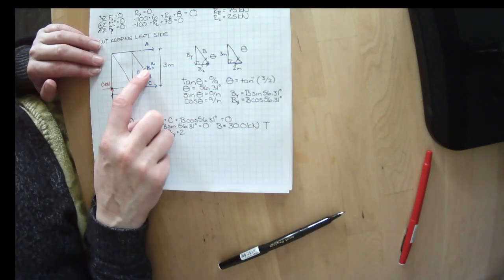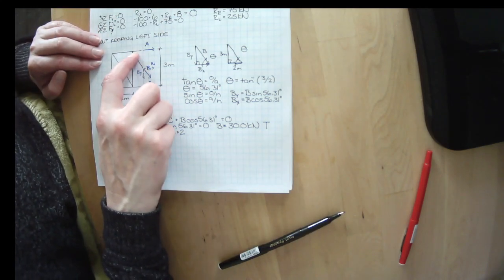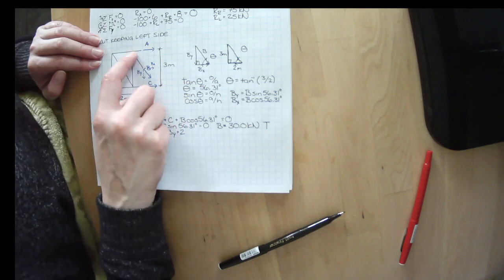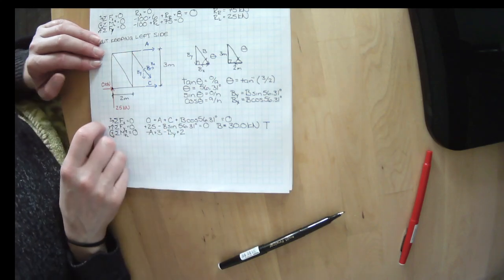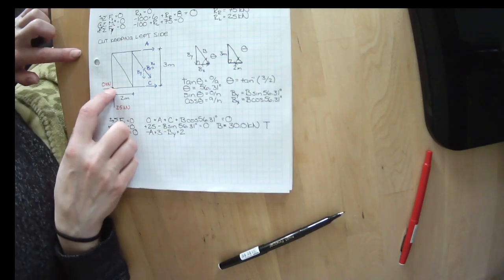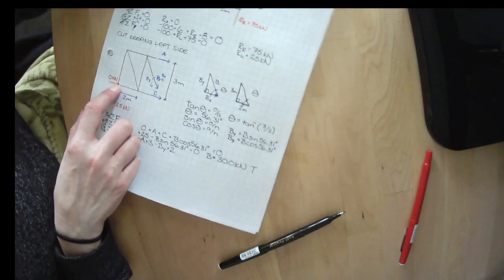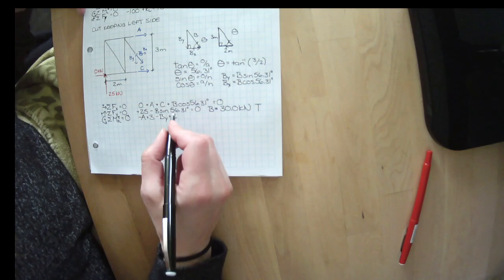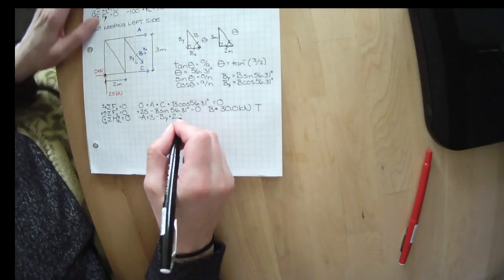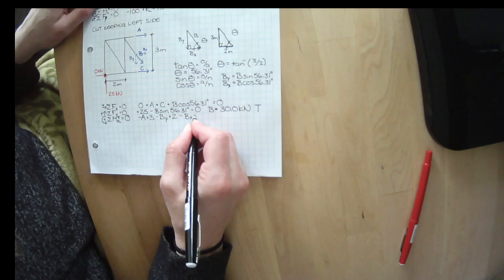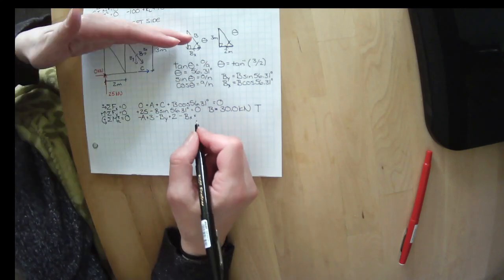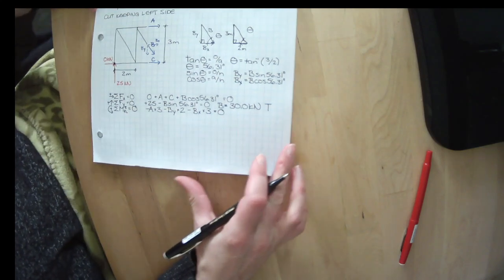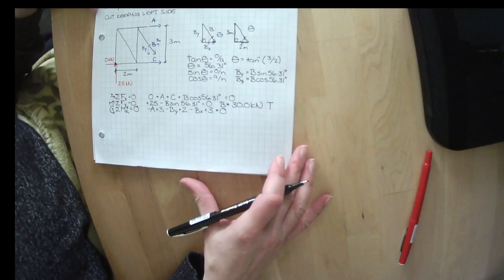BX, I know we've drawn it right here, but we could have drawn this cut right here at this point, as close to that node as possible. We're essentially talking about what's happening right there. BX then is trying to make it spin in that direction. Put my thumb down. It is also in the negative direction. And it is 3 meters away. And we want to know what it takes for the sum of all of those to be 0.